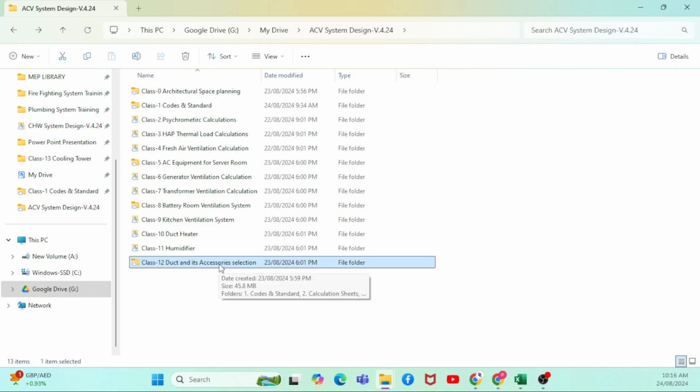Okay, so basically there is an ASHRAE standard given here to calculate the static pressure for all the ducting and the velocity pressure for all the accessories such as elbow, VCDs, louver, everything. So you can calculate as a summary sheet, spreadsheet, then you can arrive at the total ESP with the safety factor. You can arrive at the total pressure required for the fan. So basically, when you go through all this structure, you will be able to design the air conditioning system and ventilation system project. So this is what you will learn after completing this session. Thanks everyone.